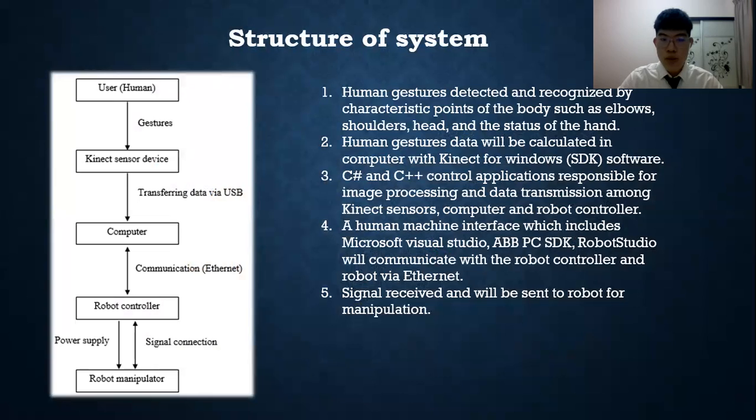Between the transmission, a human-machine interface which includes Microsoft Visual Studio, ABB PC SDK, and Robot Studio will communicate with the robot controller and the robot through the Ethernet connection. Between the robot controller and the robot manipulator, there are signals being received and sent for the robot manipulations.